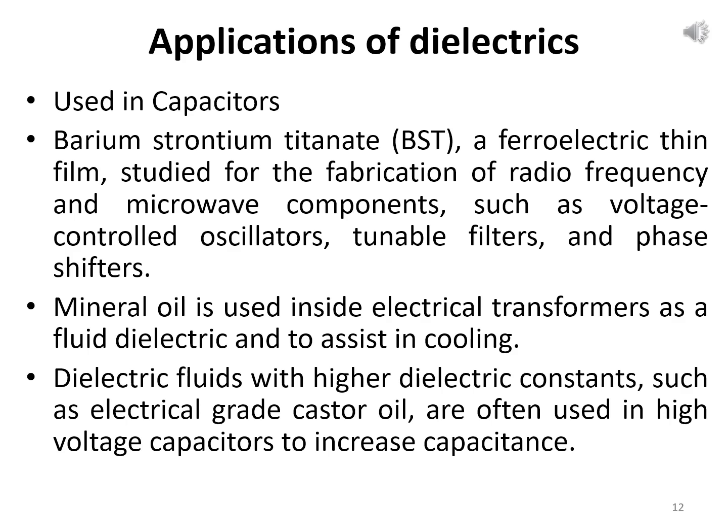So dielectric materials can be solids, liquids or gases. In addition to this, high vacuum can also be useful as a dielectric, even though its relative dielectric constant is only 1. Solid dielectrics are generally the most commonly used dielectrics in electrical engineering.